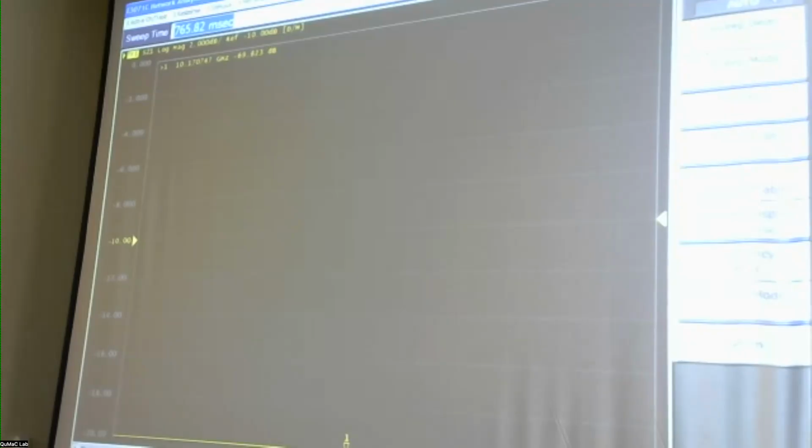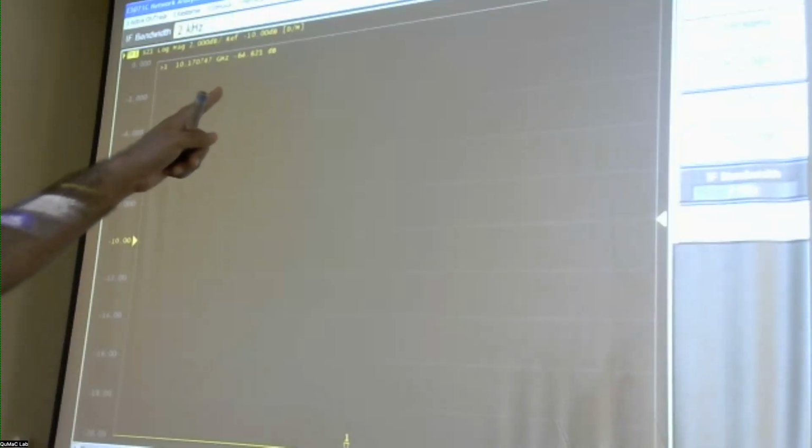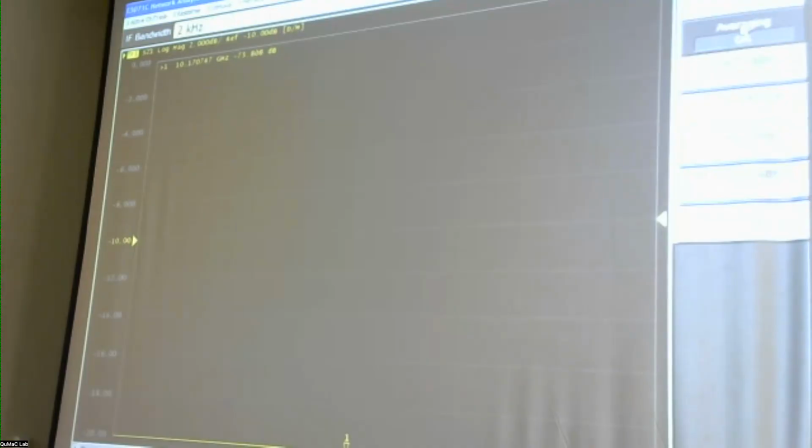But sometimes, even the slowest sweep you can do might not be enough to get enough signal to noise ratio, or you might have other reasons for wanting to sweep fast. It depends on your experimental requirements. But then you can repeat that sweep over and over again and average. So instead of sitting here and averaging, then moving to the next point, you can sweep, come back and sweep again, and then the two points at the same frequency can be averaged. That is set here by this averaging factor in the averaging menu, and for that you have to turn the averaging on here.